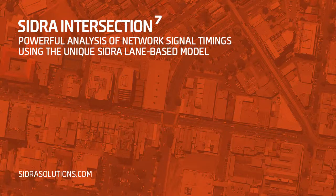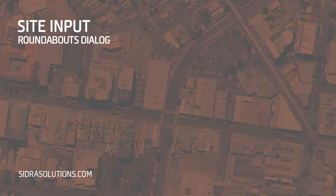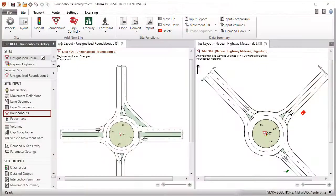In this video, we'll show you how to use the Roundabouts Input dialog to specify input parameters specific to roundabouts in SIDRA Intersection 7. Before we begin, please note that the Roundabouts Input dialog will only be available when the site type is an unsignalized roundabout or a roundabout with metering signals.